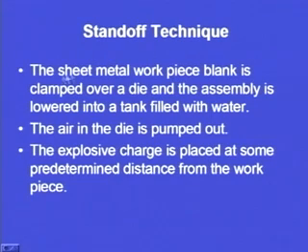In case of standoff technique, the sheet metal workpiece blank is clamped over a die. Here the die arrangement is there because the die will directly create a cavity of the shape that we want to produce. If we want to give a sheet metal a particular shape, the die will have the exact replication of that shape. The sheet metal workpiece blank is clamped over a die, and the assembly is lowered into a tank filled with water.